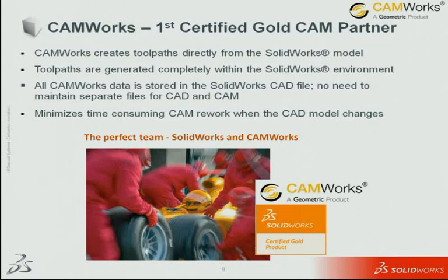As I mentioned, we were the first certified gold CAM partner, and CAMWorks creates toolpaths directly from the SolidWorks model. The toolpaths are generated completely within the SolidWorks environment, so you never have to leave SolidWorks to go into CAMWorks. They are fully integrated, and all the CAMWorks data is stored directly in the SolidWorks files. CAMWorks works with both part and assembly files as well.